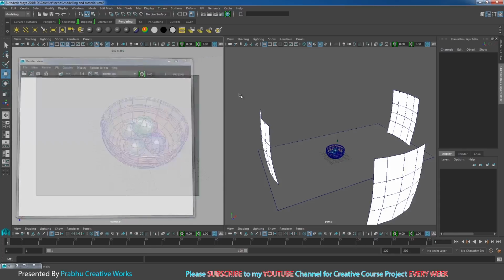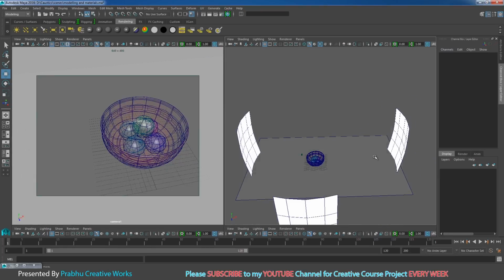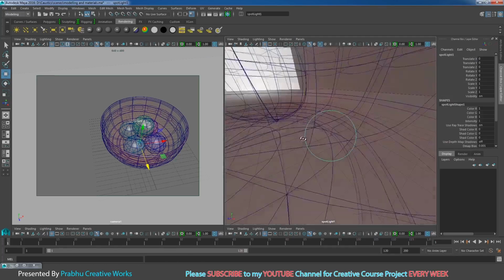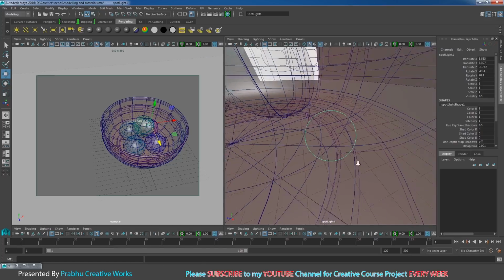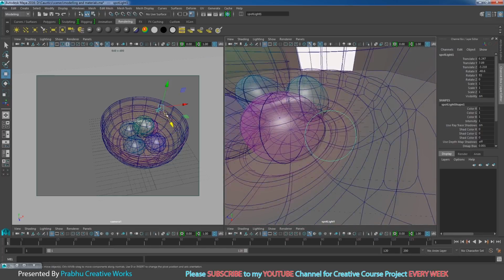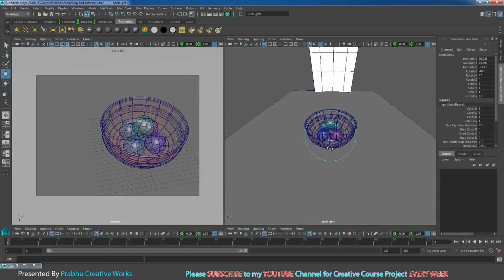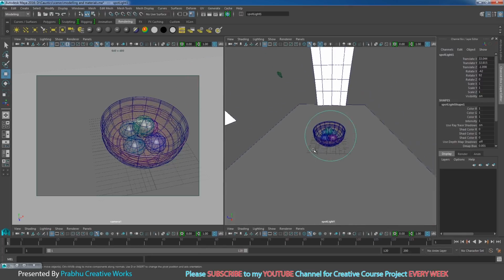So now I want to set my light over here. Go to rendering and click on create spotlight. When the spotlight is selected, go to panels and choose look through selected. That means you will be able to see through the spotlight. When I adjust my viewport, the spotlight will be adjusted. See here, you want to angle it like this.